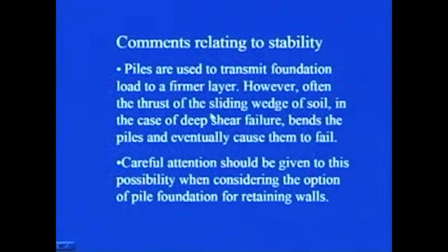However, often the thrust of the sliding wedge of the soil in case of deep shear failure bends the pile and eventually causes it to fail. So we need to make sure that when piles are used, they do not bend and fail. Careful attention should be given to this possibility when considering the option of pile foundation for retaining walls.